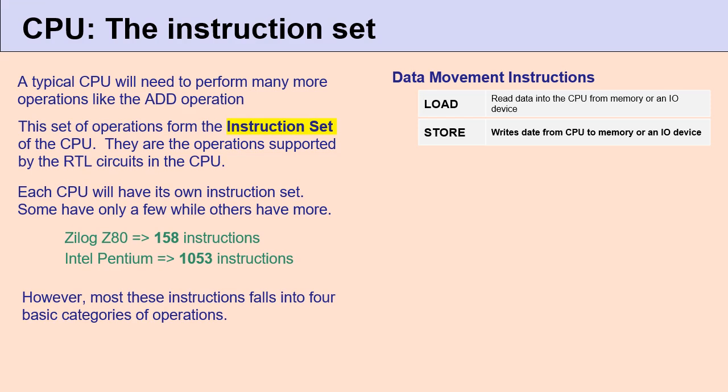Another category of instruction would be mathematical operations, like the add operation that we discussed earlier. Similarly, CPUs may also support operations like subtraction. In some CPUs, you may not get a separate instruction called subtraction, but instead you get an instruction which can convert a number to a negative value. So with that, you can use the add operation itself to do the subtraction. You convert the number to a negative value and then add it with the other value to get the subtraction effect.